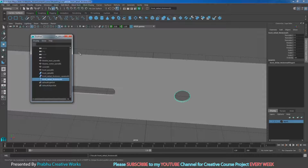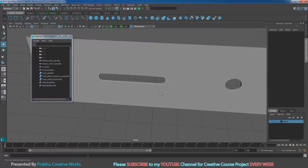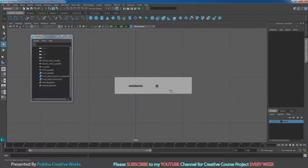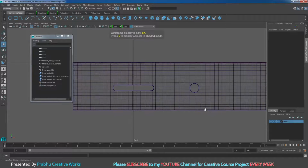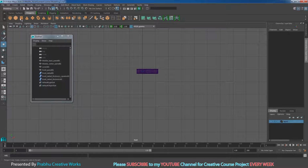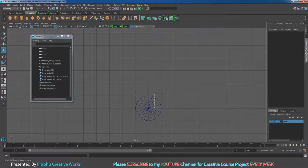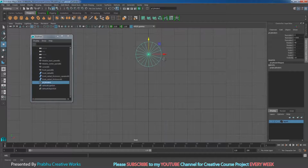So now you want to make one over here for our mesh. So go to front view, press 4 on the keyboard. So now click on polycylinder, press E and rotate in X 90, press W and move in Y.